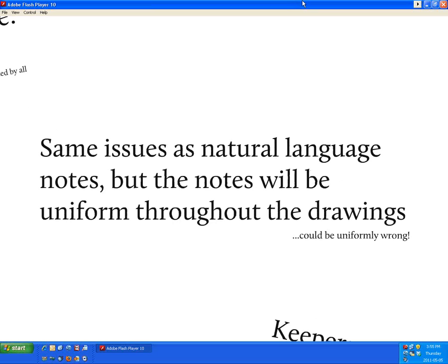And we might explain that by keynotes we mean a system where we're not talking about numbered plan notes where everybody uses that, but on wall sections, details, and elevations where numbered or alphanumeric designations completely replace all natural language notes, or essentially all notes.